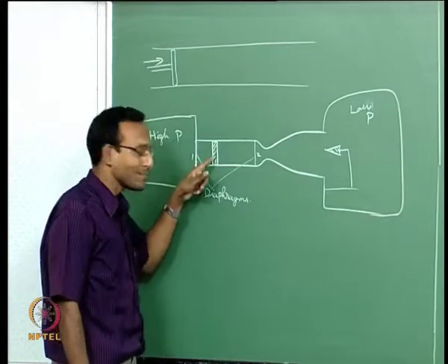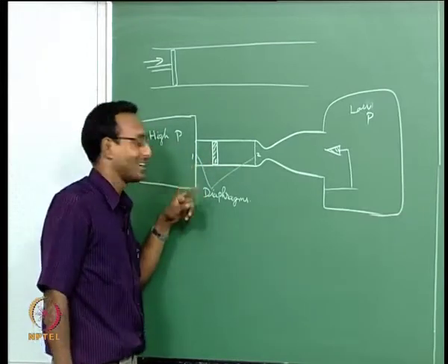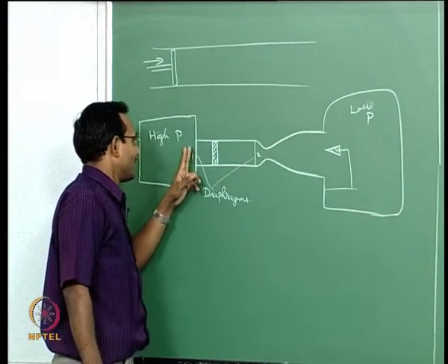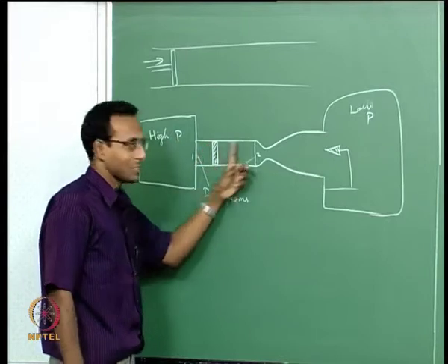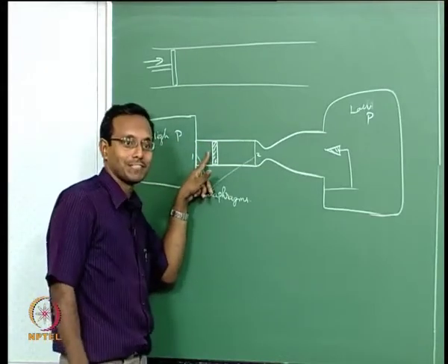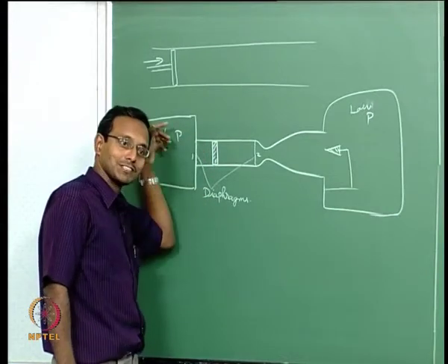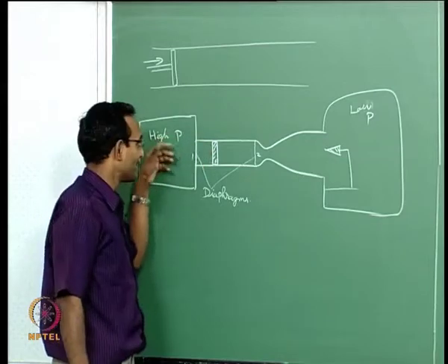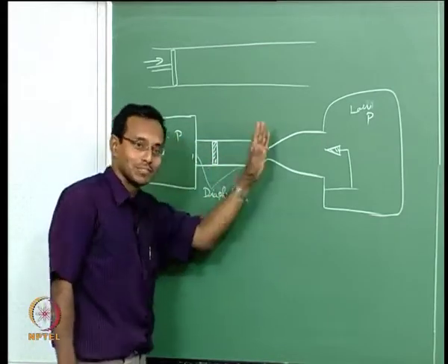Okay. If I have a piston, there is something special that will happen now. That is why the piston is there. Okay. Now, this shock develops, and when it reflects back, when this wall starts moving, there will be an expansion fan going that way and killing that compression reflection back. Okay. So, eventually this piston will start getting force from this side also. This high pressure will start pushing the piston also, but it got an initial momentum this way and it is moving in.